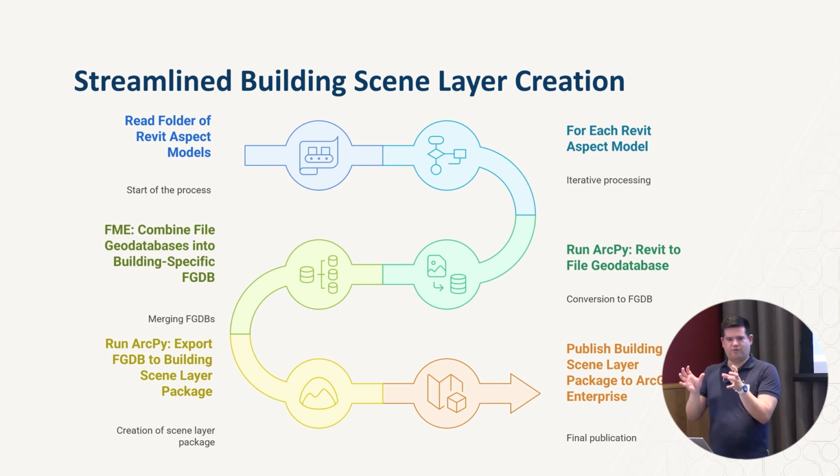So I run FME to run a series of ArcPy commands to make a large model. I also told you I have different models per discipline. In the end, in ArcGIS, I want to have one building, so I have to combine BIM files. I tried to use 5 BIM files for one command, and it had, I think, a memory leak, because one model was fine, 2 models took, I think, a day, 3 models didn't finish after a week.